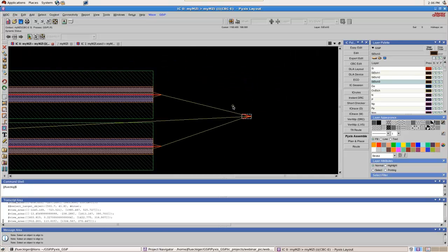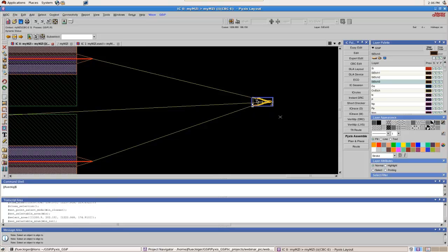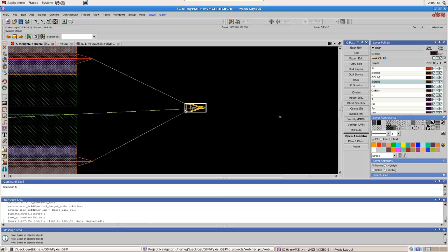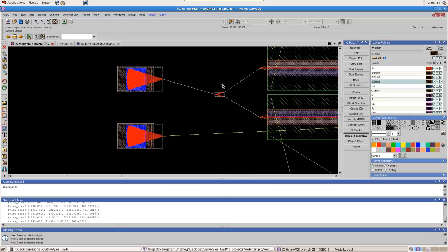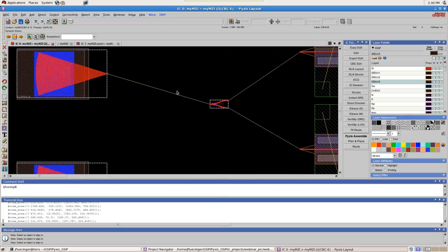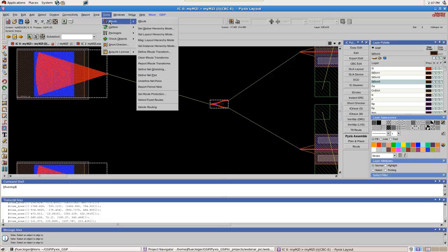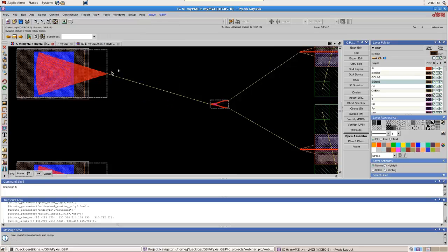And I guess we are done here. So let's arrange the Y branch here. So this one is basically the distance between the Y branch and the phase shifters are pretty much the same. And now what we like to do is to set the waveguide. And you're going to use a tool called iRoute. So with iRoute, we're just going to go and set all the waveguides.